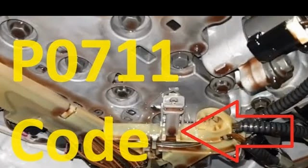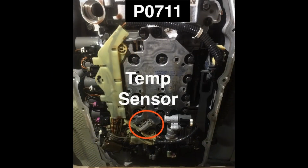Condition 2: a transmission fluid temperature at startup is 129 to 149 degrees Celsius (264 to 300 degrees Fahrenheit). Vehicle speed exceeds 8 km per hour (5 miles per hour) for a cumulative 300 seconds (5 minutes). Transmission fluid temperature has not varied by more than 2 degrees Celsius (4 degrees Fahrenheit) since startup for 80 seconds.